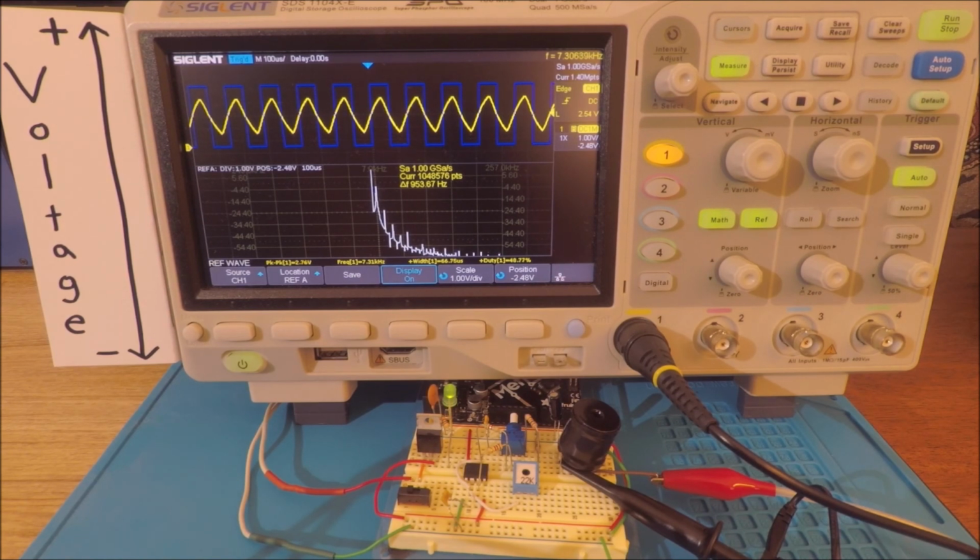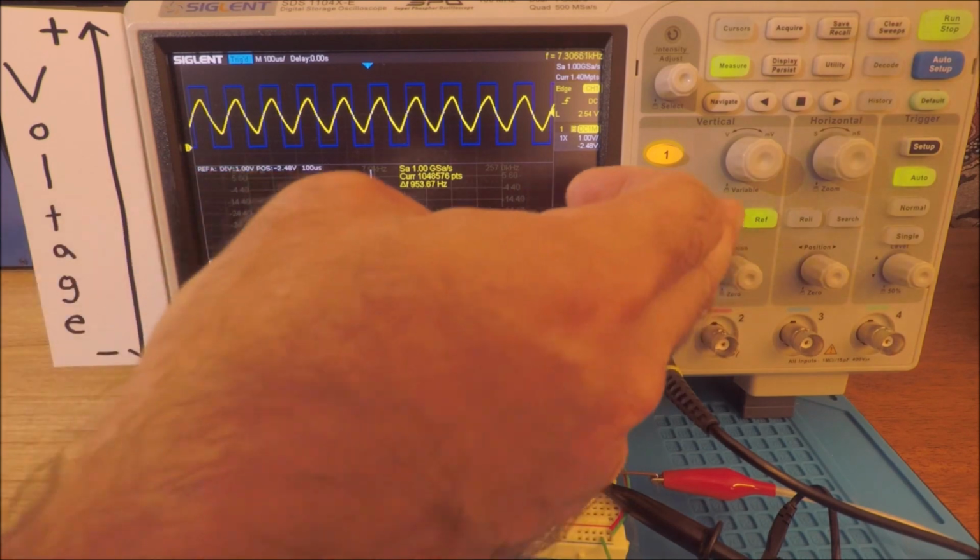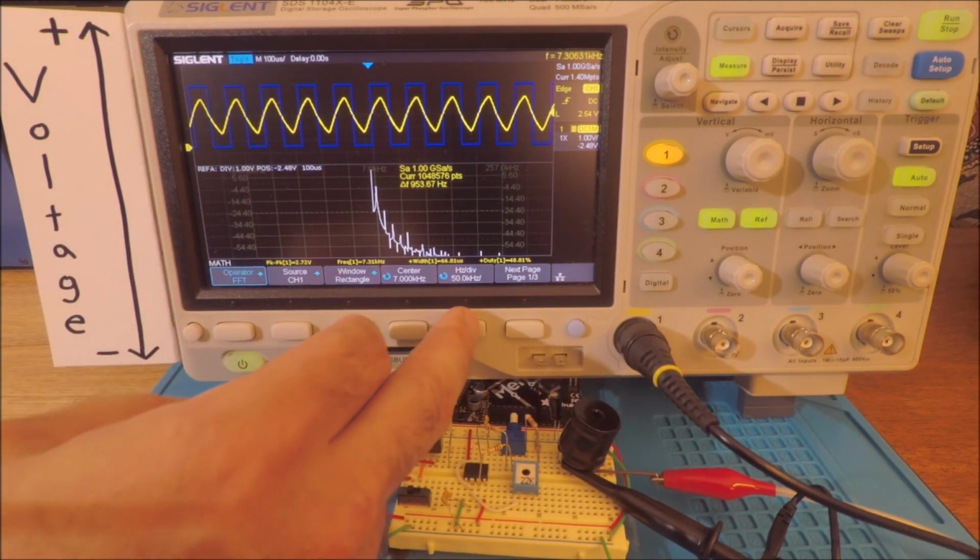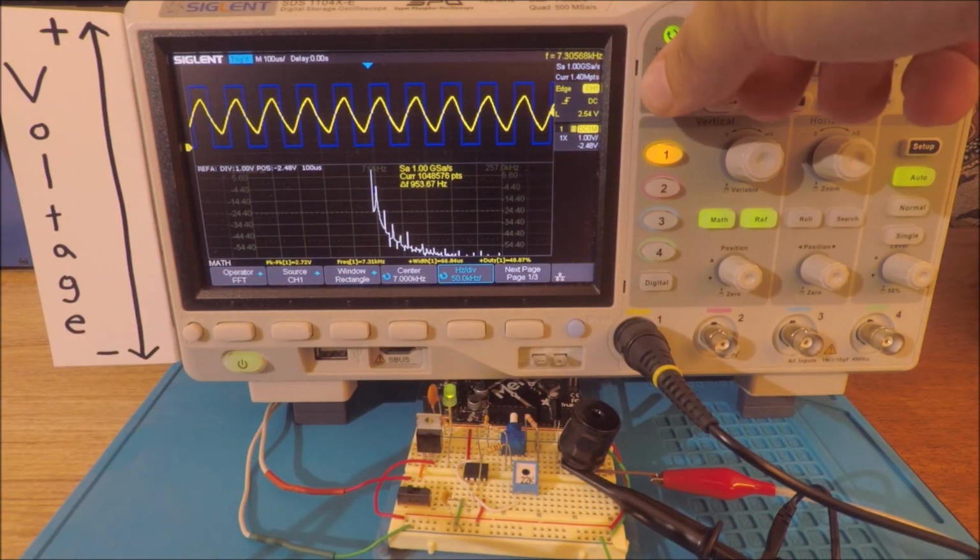Also interesting is I can hear the resonant frequency of this filter audibly in the room. I'll bring up the other microphone. It's a little irritating because it's at 7.3 kilohertz. But that's in the audible band, so we are hearing this oscillation that we can see in the time domain. We'll turn that down because it's distracting. We can zoom in the frequency domain to take a look at the attenuation of the harmonics.